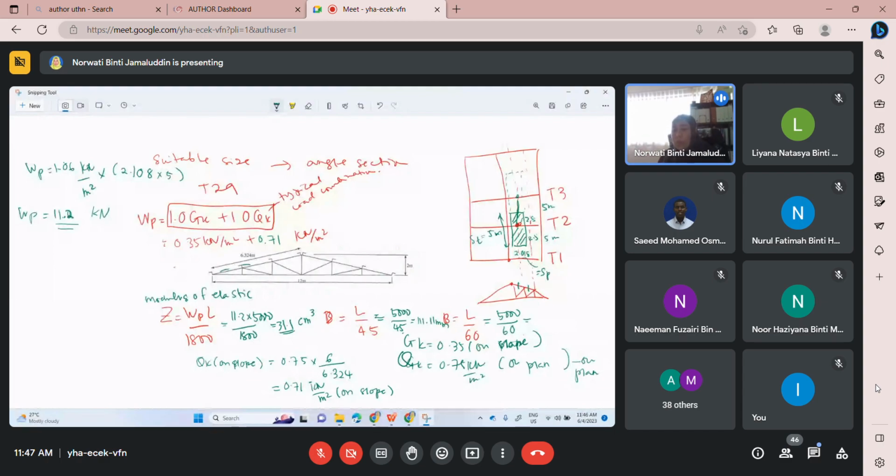Okay. So set rod, of course, there's no load on set rod except its own self weight. We are afraid that the purlin will bend because purlin normally spans until 5 meter long.